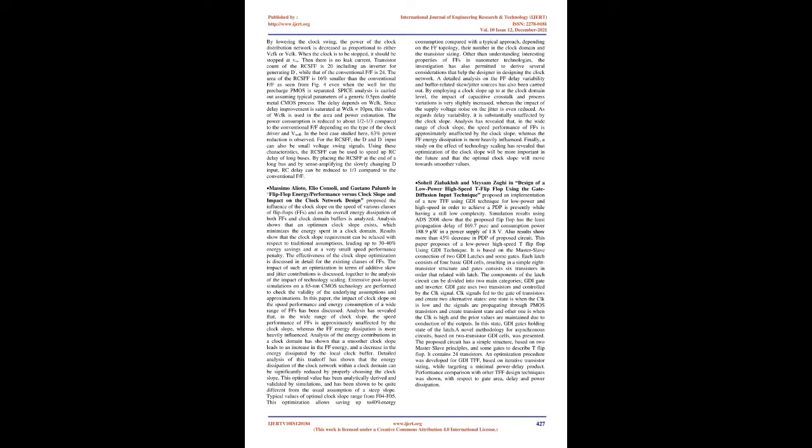This CDFF not only reduces the internal switching activities, but also generates less glitch at the output, while maintaining the negative setup time and small D-to-Q delay characteristics. With a data switching activity of 37.5%, the proposed flip-flop can save up to 39% of the energy with the same speed as that of the fastest pulsed flip-flops.